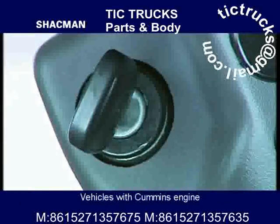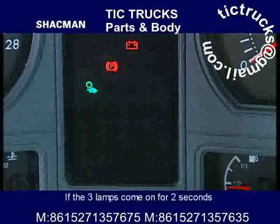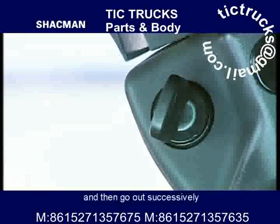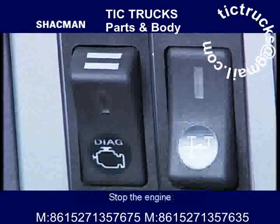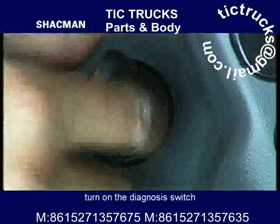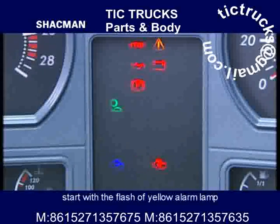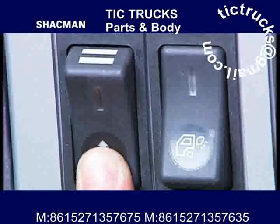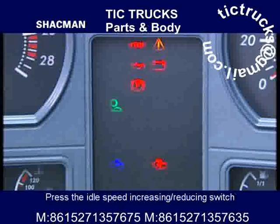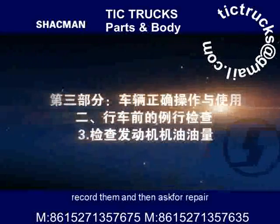Vehicles with Cummins engine. Turn on the ignition switch. If the 3 lamps come on for 2 seconds and then go out successively, the engine is in good condition. Read the trouble code as follows. Stopped engine. Turn on the diagnosis switch. Turn on the ignition switch. Start with the flash of yellow alarm lamp. Read the 3-digit trouble code from the red lamp. Press the idle speed increasing or reducing switch for reading the next or previous trouble code. Record them and then ask for repair.